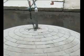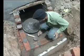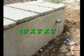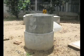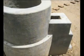After the construction of the biogas plant, the outlet tank is constructed. The size of the outlet tank is 10 feet by 3 feet by 3 feet. 2 outlet pipes are fixed in the outlet tank to drain out the excess of slurry. Similarly, a circular inlet chamber is constructed to feed the biogas plant. After the completion of the biogas plant, we make a connection of the biogas plant to the kitchen.